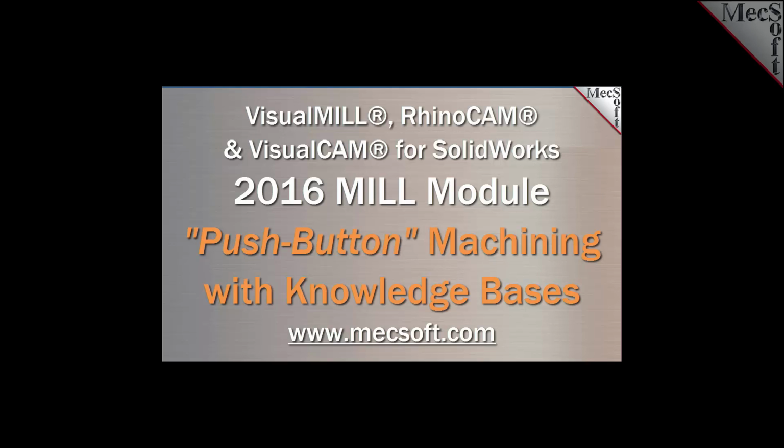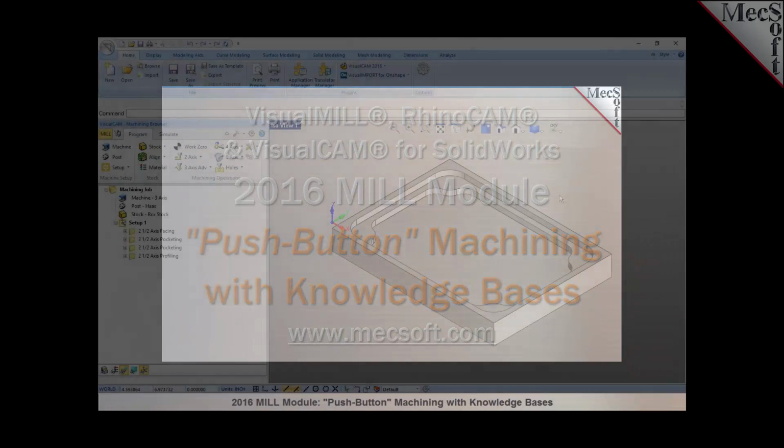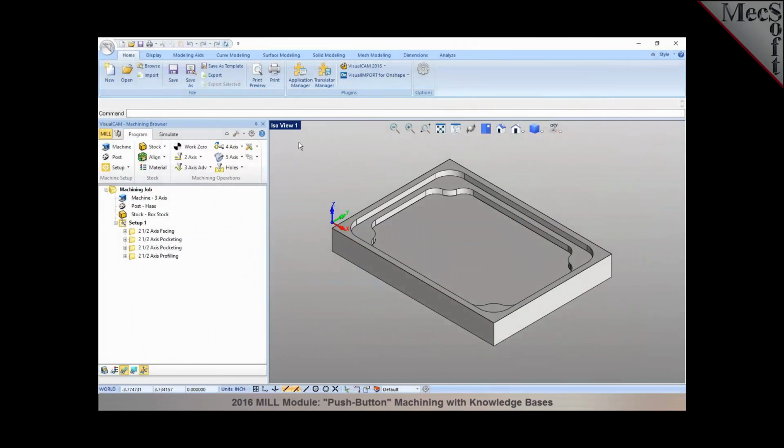What this allows you to do is, once you have machining operations programmed in your current file, these operations can be archived and saved into a knowledge base, which allows you to take these operations and apply them on other files, or maybe a family of parts that you may be working on, so you can take advantage of reutilizing these operations. Now, saving operations to a knowledge base will save or archive the entire strategy of operations.